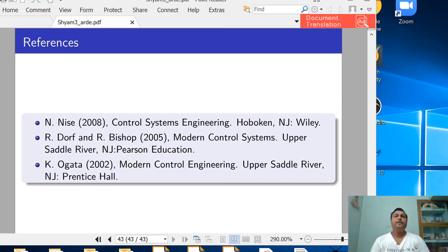If not, then performance indices will be given, and from there you calculate where the closed loop poles will be located. Once you know the closed loop pole locations, you can find the desired characteristic equation. Then you have to follow whether any method is specified. If a method is specified, using that method you can find the gain matrix K to place the poles at the desired location.